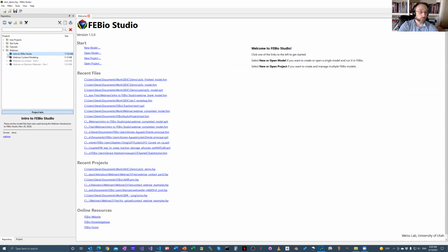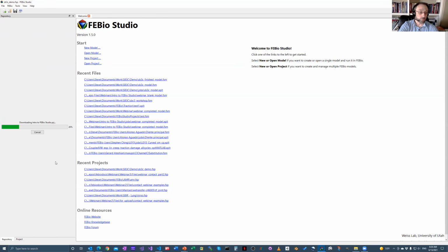What we're going to do is start with the same model that we used in the Intro to FEBio Studio webinar. In fact, most of this demo will follow this presentation quite closely, and the main reason for that is that it covers quite a few different features in FEBio Studio that are not too advanced to start with. If you haven't already, go ahead and download this project, and the way to do that is to just right click on the project name and click download.